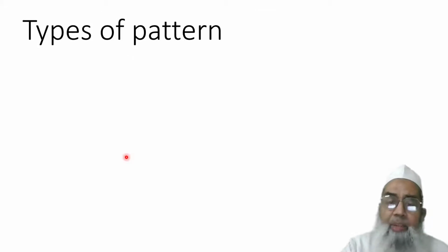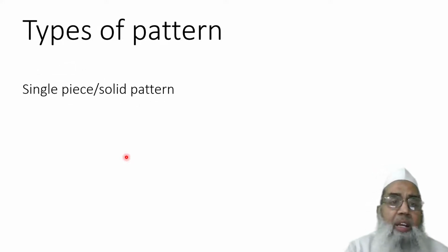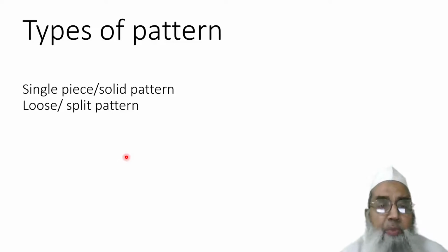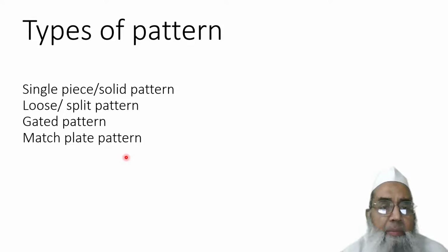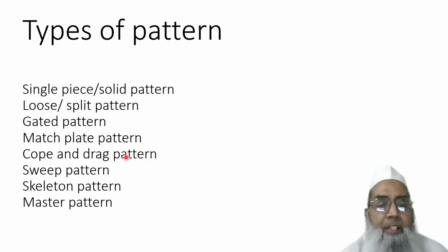Now therefore, to have the cavity in the mold, we need a pattern. Now there are different types of patterns, like single piece or solid pattern, loose or split pattern, gated pattern, match plate pattern, cope and drag pattern, sweep pattern, skeleton pattern, and master pattern.